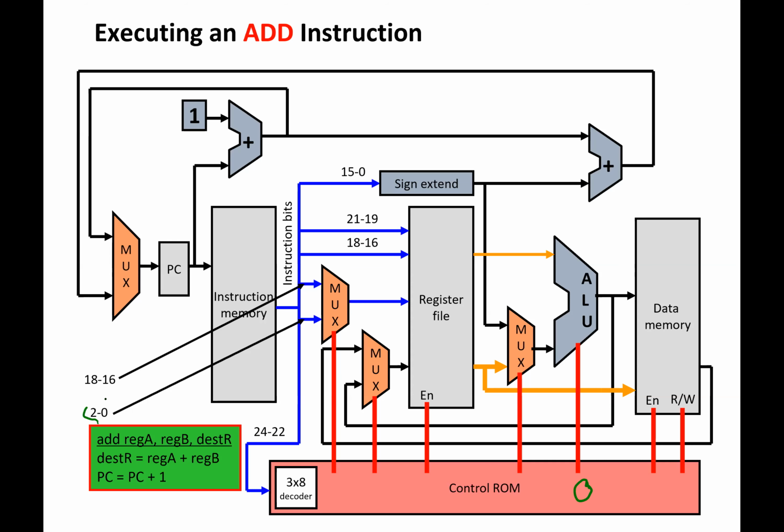We're using the destination register as the index. So as a reminder, these are all indices here. These two are the read indices. This is the write index, and then this is write data. And then this is write enable. So the write index, we're going to use the destination register, which is the bottom input of this mux. So that's going to have to be a 1.